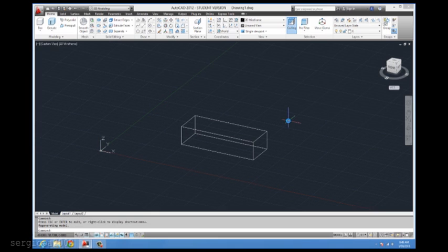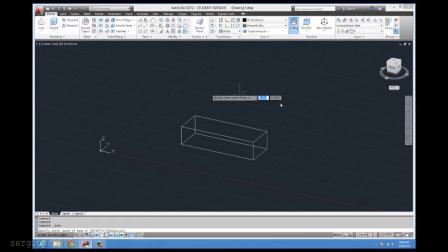Now not only can I create boxes, okay, I can also create all sorts of things. So here in the modeling tab, I can just click on the box icon and you see that you have different kinds of primitives like cylinders, cones, spheres. So let's just draw, for example, a cone. I click on cone, I click where I want the center to be, I define one of the dimensions, the width, so to say, and then the height. I can go either up or down in relationship to the plane. Let's go up, and that completes my cone.